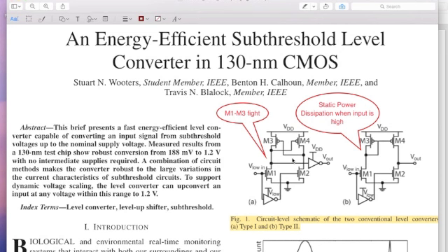So how do you solve this problem? Firstly, you recognize what the problem is. The problem is that I am unable to overcome the PMOS. PMOS is turned on too hard. So what can I do to weaken the PMOS, or what can I do to strengthen the NMOS? One approach to strengthen the NMOS is to use larger sizes. But it turns out in the subthreshold region, the drive strength drops exponentially, so the size also grows exponentially if you want to match the drive strength of the PMOS which is in the superthreshold. So it just doesn't become a practical solution.